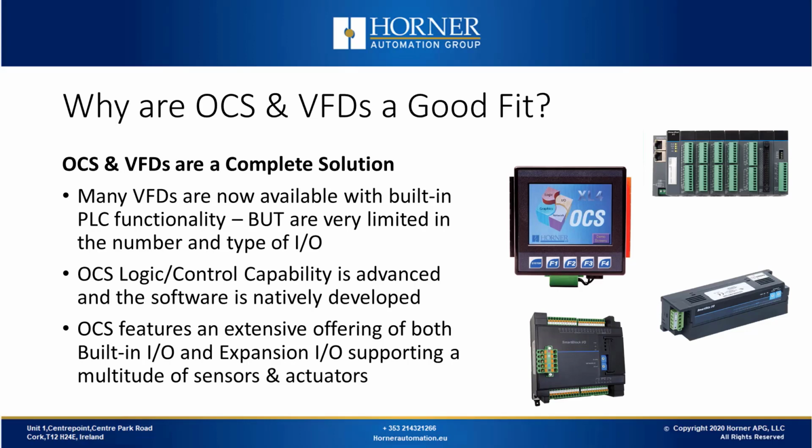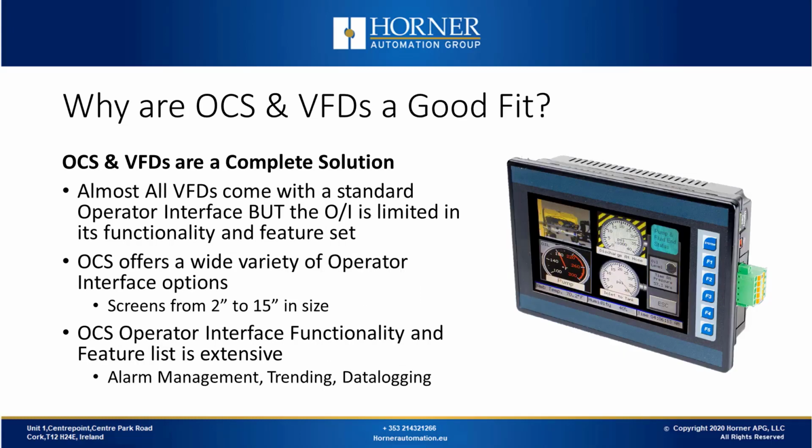Another reason they are the complete solution is the fact that while variable frequency drives have I/O built into them and the ability to interface with some different types of sensors and actuators, they are pretty limited when it comes to I/O. Most variable frequency drive manufacturers don't have a lot of expansion I/O for their drives. The OCS has a wide variety of I/O with the option of additional I/O expansion. There are a lot of sensors that you typically wouldn't find interfacing with a variable frequency drive. For example, RTDs and thermocouples are not something you would typically connect directly to a variable frequency drive.